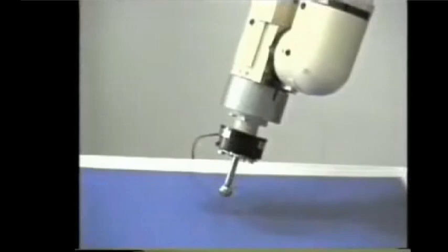Remember that this robot has an open control architecture, open CS3 or something like that. It is an open facility made available by Comau for research purposes and beyond. So you can really modify the controller and enter at the current or torque level in these cases.